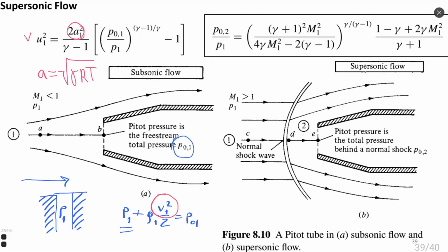But I don't believe that this is a very big issue, right? It can be quite precise, by estimation from altitude, or by measurement of onboard temperature. But we need temperature definitely, because compressible flow equations require the speed of sound for calculation.